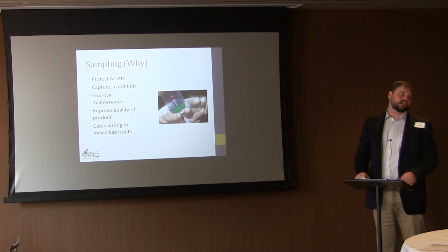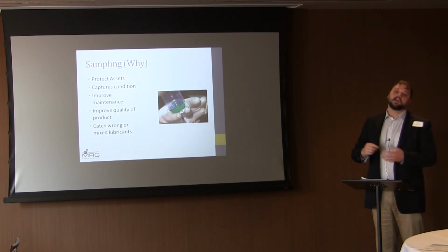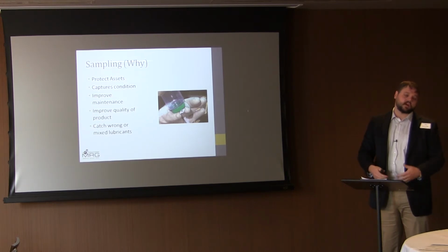It's set at a certain pressure, so it's always going to take the correct amount of volume, leaving headspace in the bottle. It takes out any kind of headache of taking a sample for you and makes it consistent. All you have to do then is twist your white handle and lock the bottle, and the bottle's never been opened. So you don't have to worry about dust or anything from the environment dropping in and contaminating your sample.